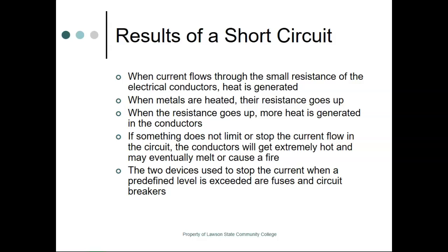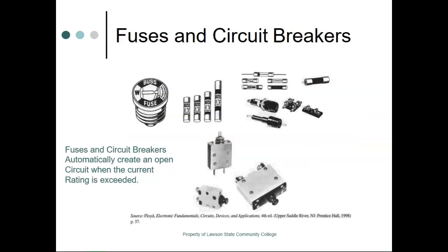Like I said, before we went to circuit breakers, a lot of homeowners would just go to the hardware store and get bigger fuses. Well, the fuse won't give up before the wire does at that point. That's one of those things I always try and explain to everybody. You don't want to get something too big because even though it's popping all the time and that's a little expensive, you might want to start looking at what you can unplug instead of just trying to put in a bigger fuse, which causes more havoc. Of course, almost nobody ever really thinks that that's going to happen to them, but, you know, hey.